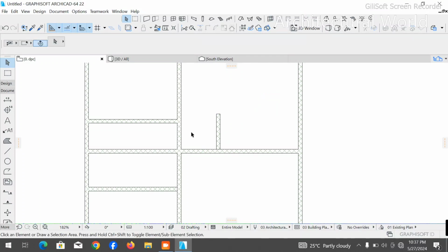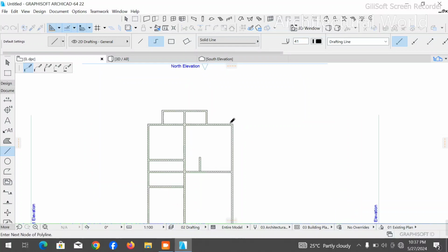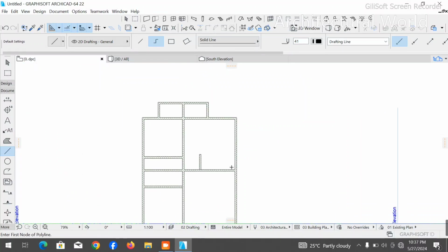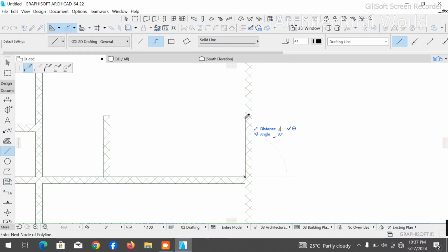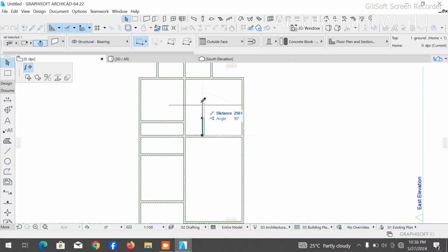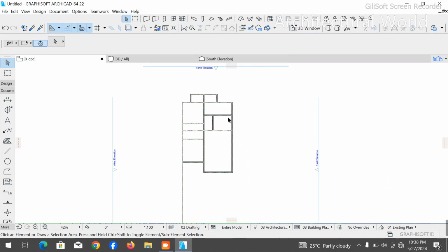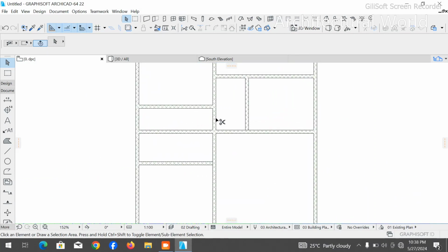We'll bring this wall here. Then we'll make this to be 2.6 meter or 2.5 meter. Okay. What's left? 1.9. No. Let's make this to be 2.4 meter. Then the leftover becomes the width of the kitchen. Okay. We have this here. We align this to this. We copy this to this. Okay. Align it to this. You bring down this. There's a kitchen balcony. Take away this lobby. So everything is going to be connected.